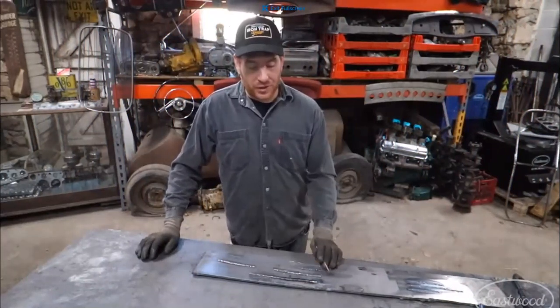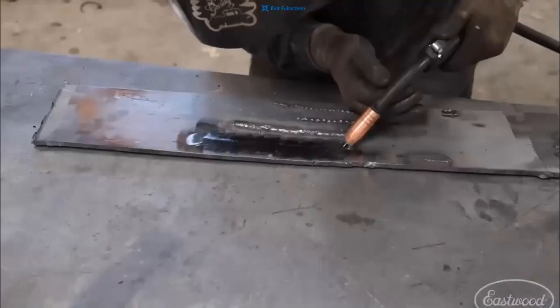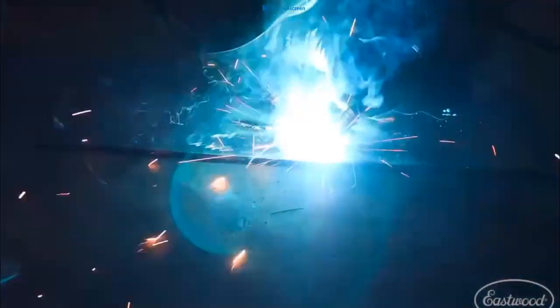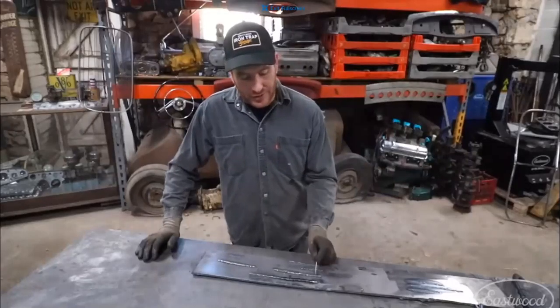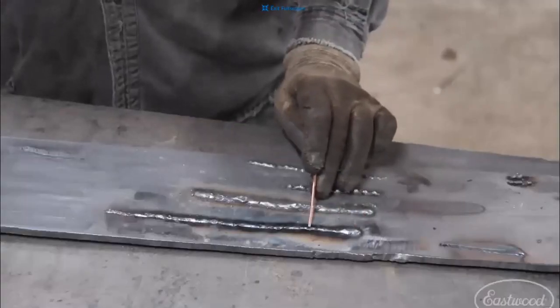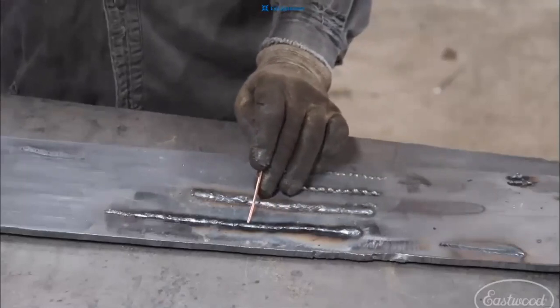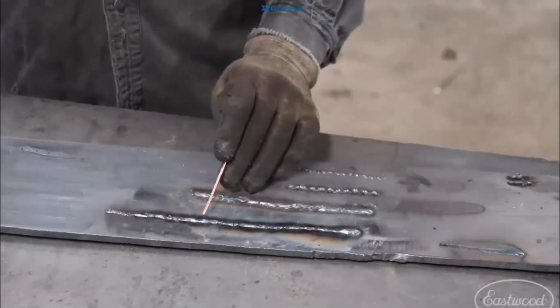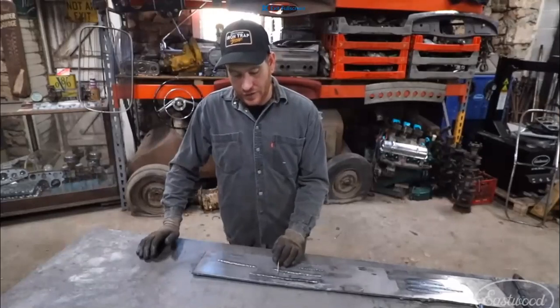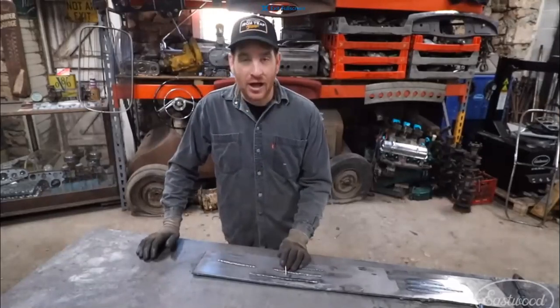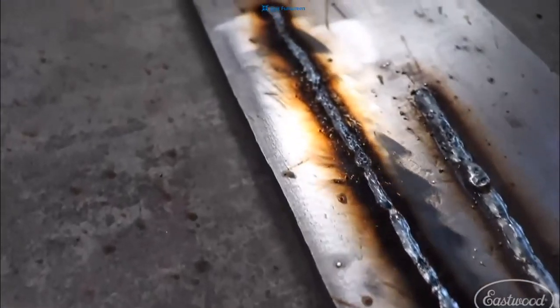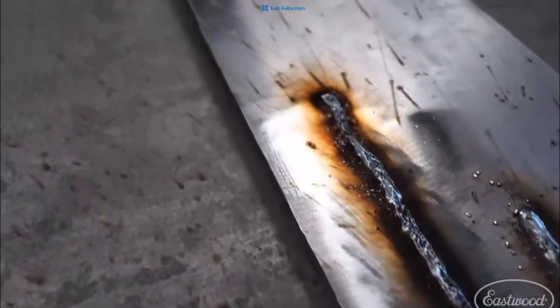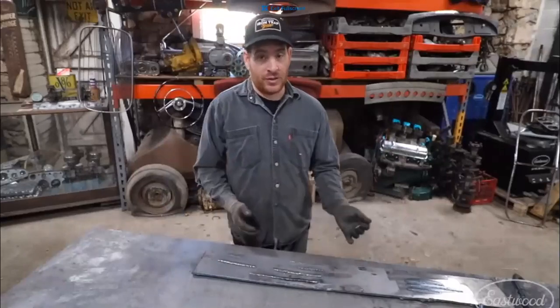So I did a weld here where I moved far too quick across the panel. I had the correct settings as per the recommended settings on the welder, but I traveled across the panel far too quick. What you see with the weld is that it's kind of dragged out and it gets very thin, and there are even almost some gaps in the weld along the way. And then finally, as I started moving extremely quick at the very end, I was actually moving quicker than the shielding gas was able to cover the area, and we started seeing some porosity in the weld at the very end, which obviously is going to be a problem.